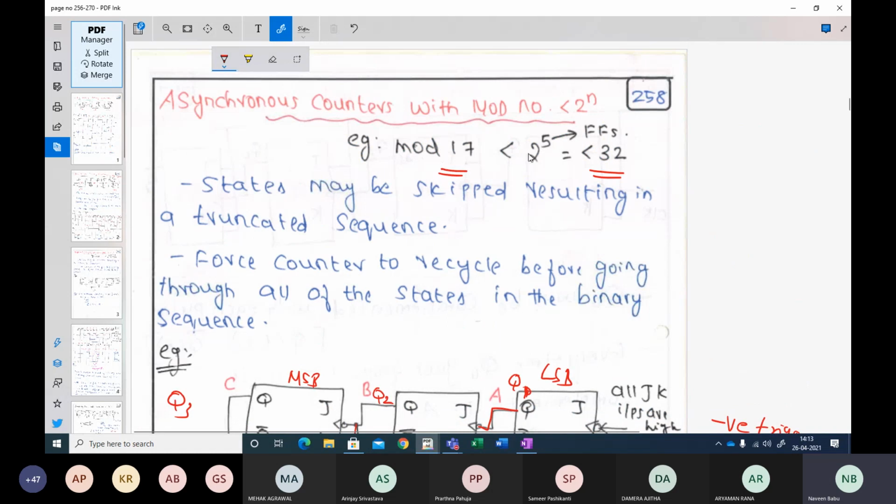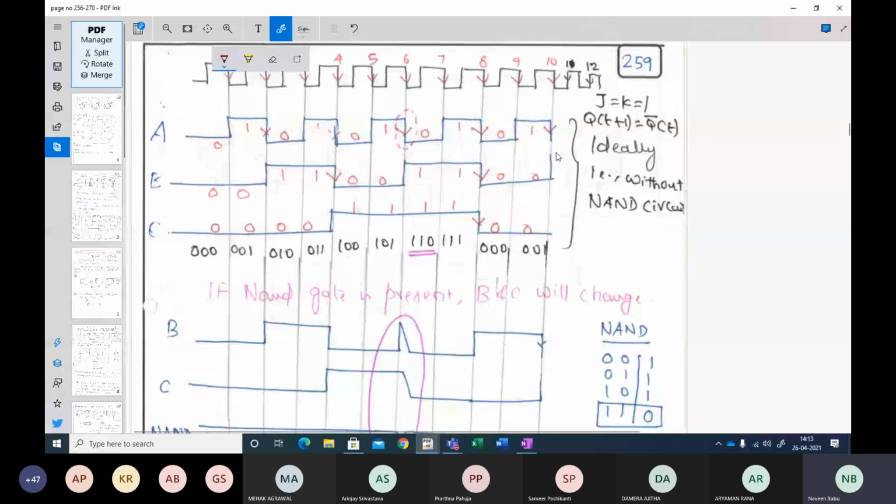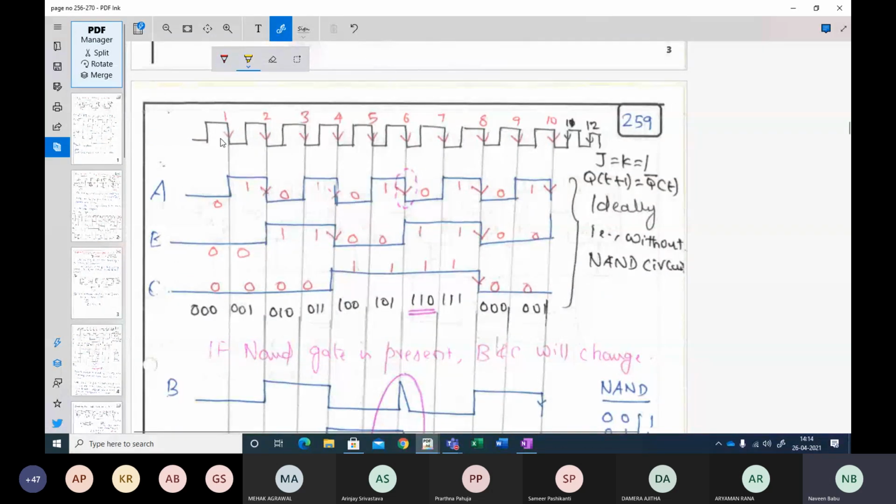Okay, so this is the timing diagram that takes place. Maybe I'll quickly touch upon the timing diagram also. This is a negative edge triggered flip-flop because we have been connecting Q to the next clock. So hence negative triggered. Now what happens? There is a counting sequence. Whenever there is a negative transition across Q0, there is a transition taking place. So initially it counts from 000, 001, 010, 011, 100, 101. When we have 110, then your flip-flop must be reset here.